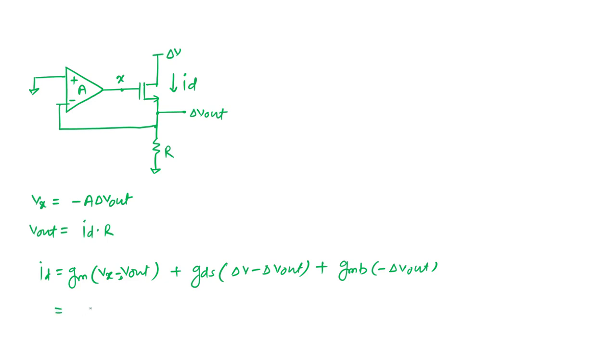So what does minus del V out mean? What we can write is GM plus GMB plus GDS, where I will again ignore these things. I am just writing to make it clear, plus del B GDS. I am writing GMB and GDS again and again so that you become habitual of writing these things in your current equation, so that you can directly find it when there is a body effect consideration. Okay. So this is the ID.